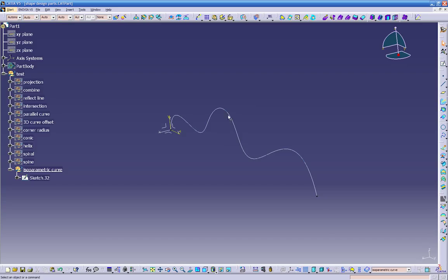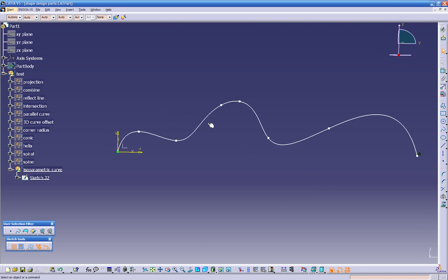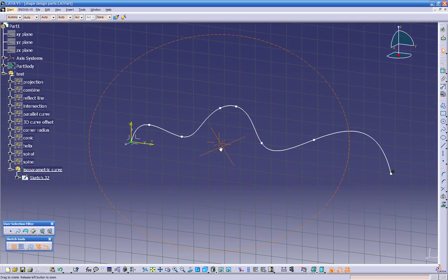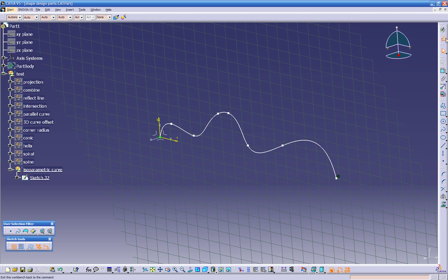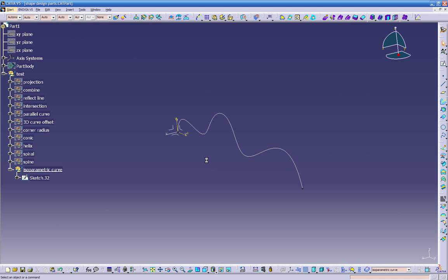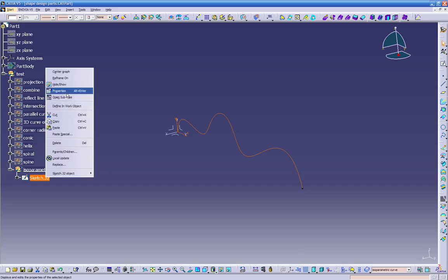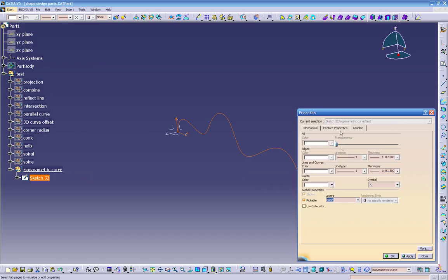What am I going to do? Because I need to create a couple more sketches over here to create a multi-section. What I'm going to do, I'm just going to copy this, move it over, and just edit those points in here, and I'm pretty satisfied with that. So it saves me more work. So let's copy. Let's make this main. Let's rename it to main sketch.